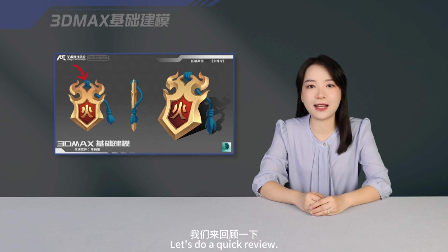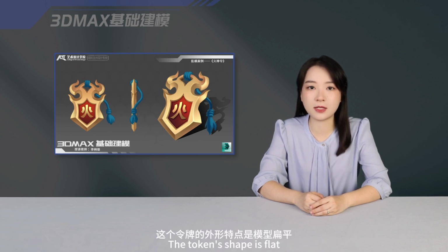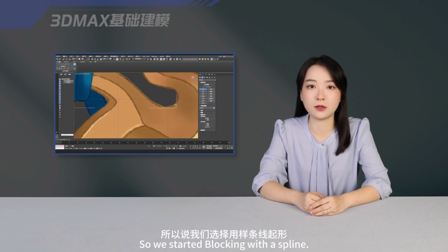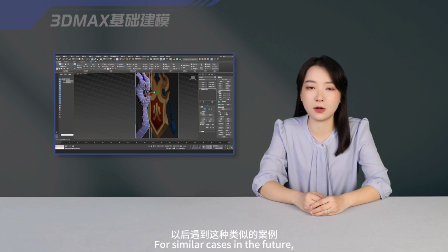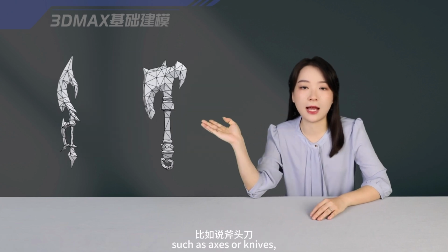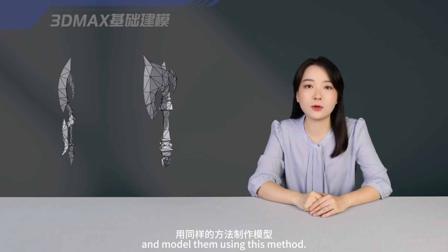Let's do a quick review. The process of making the token model. The token's shape is flat and irregular in outline. So we started blocking with a spline, then used editable poly to extrude thickness. For similar cases in the future, such as axes or knives, we can apply the same approach and model them using this method.